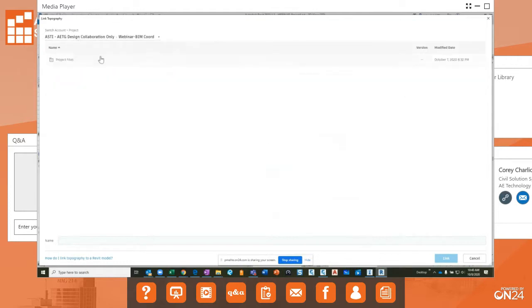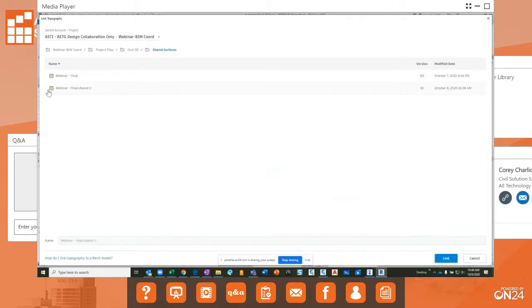Let me jump back here so we can see that I'm in my webinar BIM 360 project. I'll go into my project files, and I'm looking for that surface that I just exported. So let me go into the Civil 3D folder and shared surfaces. And now I have 2 files in here. We just created this one, webinar final shared -2. So we're going to link that file. So we'll select it, and then we'll click link down at the bottom.